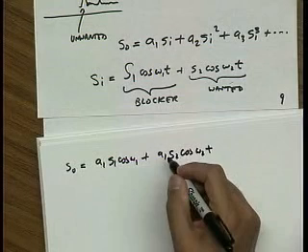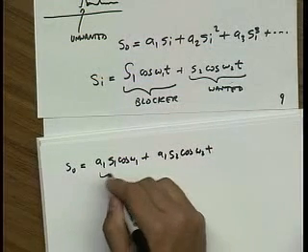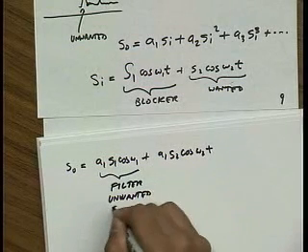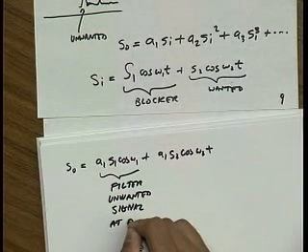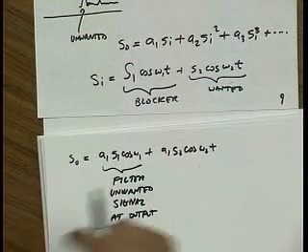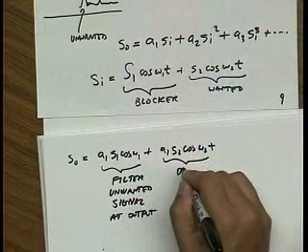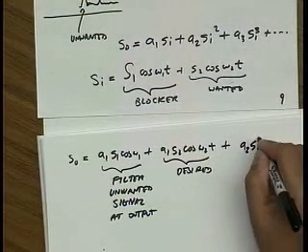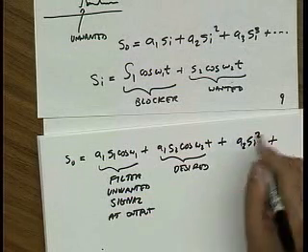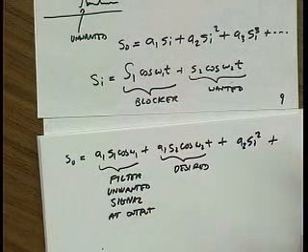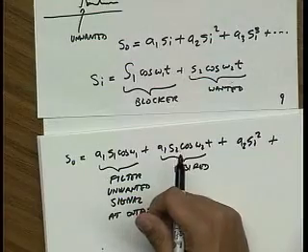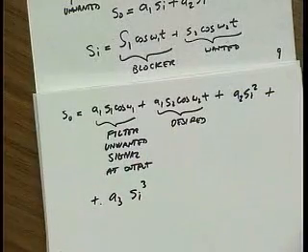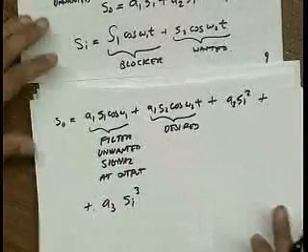But let's say that's not an issue because I'm going to filter this out. This is the desired signal that comes through. And then I'm going to have square products. This is going to lead to IM2 tones, right? But again, let's assume I can filter out my IM2 tones. And then finally, I'm going to get this cubic term. And what I'd like to show you is that this cubic term generates all the nasty stuff.